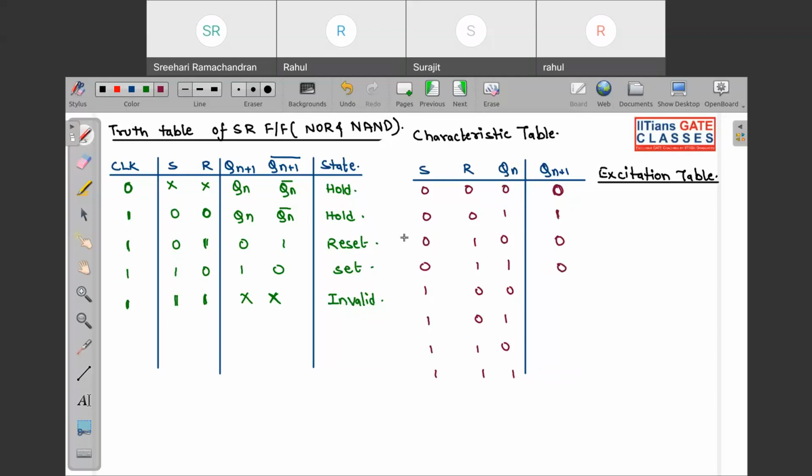So in these two cases, you have your set. Now in these two cases, you can see set input is 1, reset input is 0. So this is your set case. Obviously output is going to be 1 1. Now in these two cases, look, it is 1 comma 1. So whenever it is 1 1, we have an invalid state, and for the invalid state, you can see your present output is don't care. So put don't care over here. Okay, so this is your don't care.